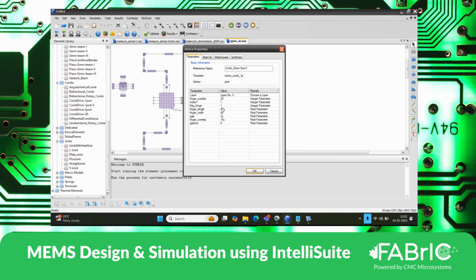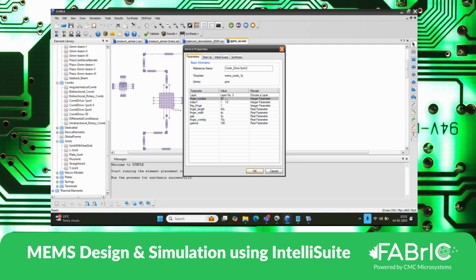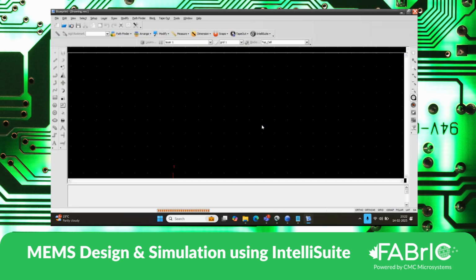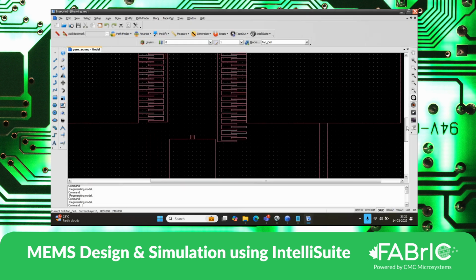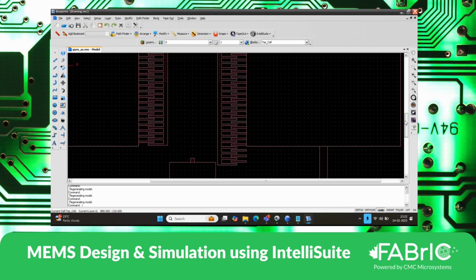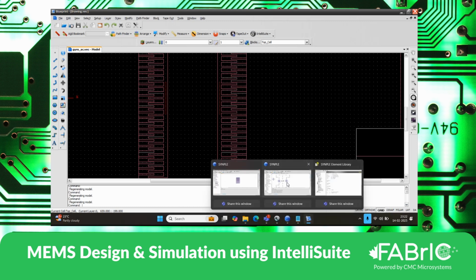Okay, so here we have this. If I increase it to 35 and save this, the number increases, but it doesn't adjust the anchor point for the fingers. For me to do that, I'll have to further adjust the width of the element, the comb drives.